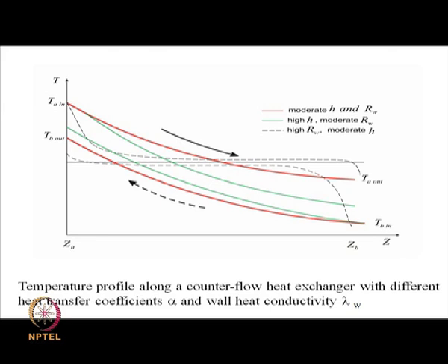So, you can think of this region as if it is an adiabatic region in which no transfer of heat is taking place. This happens when you have high effective conductivity, and for certain values of heat transfer coefficients. So, if you are designing heat exchange equipment, this is the region which is not participating in heat transfer. One has to be careful, especially in microstructure design, to see whether or not the entire length is utilized for heat transfer. So, this is something one has to look at.